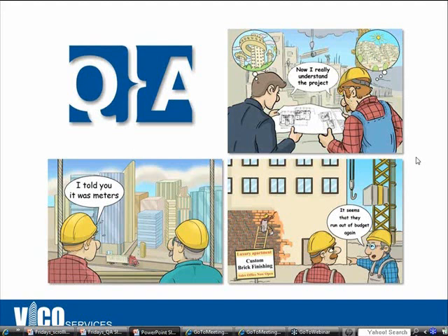Is the schedule information bidirectional between P6 and Vico? In other words, as you update the Control info, can I push that info to P6? Definitely, yes. And actually that's the recommended workflow. You update and make changes in Control, and then you push those out into P6. And we have a direct link to P6 that basically carries over not only start and end dates, but also resource information, cost information, and quantity information if available.